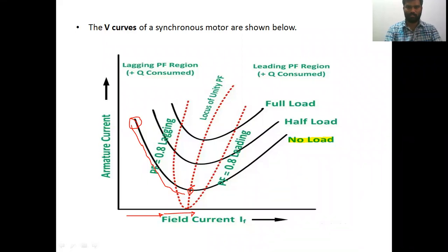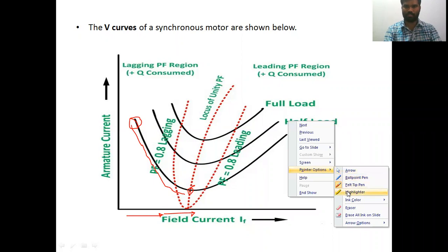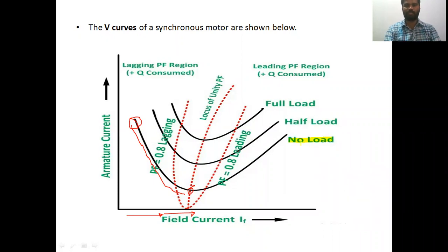when the load is again increased, the machine is set to be in a half loaded condition. Half loaded condition means, for example, if the rating of a machine is 10 amperes, half load is 5 amperes. This ampere rating is of armature current, not the field current. In our example, we have taken a 10 ampere machine, so half load will be 5 amperes. Now assume the machine is running at 5 amperes of load.